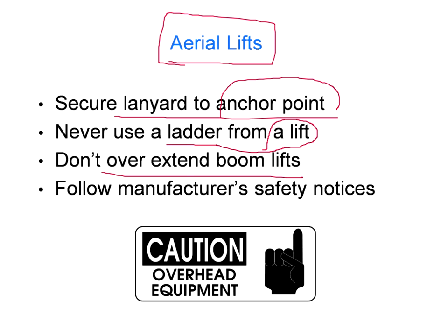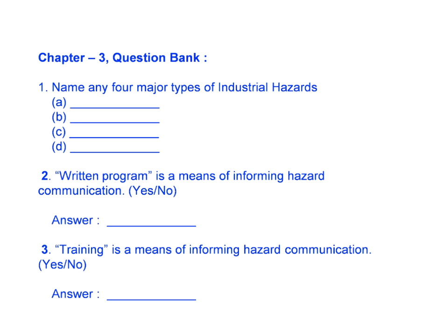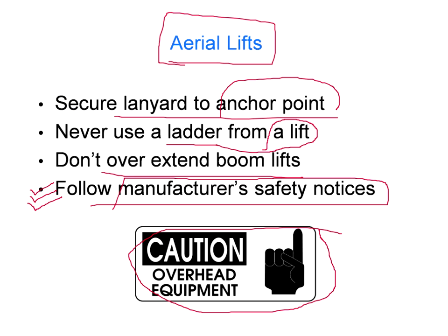Boom lifts should be used for the designed function only. You should not overuse it. Follow manufacturer safety notices. This is very, very important. Okay, so this is caution, overhead equipment. You should not use overloads beyond what it is designed for.